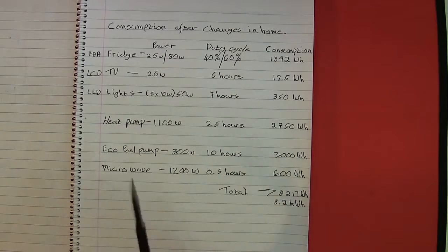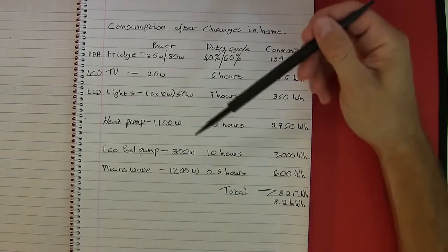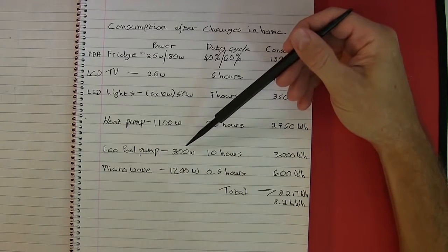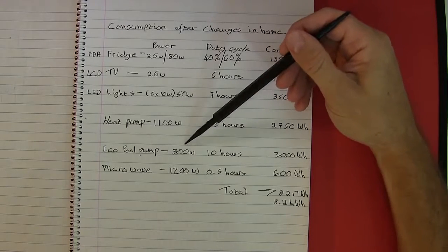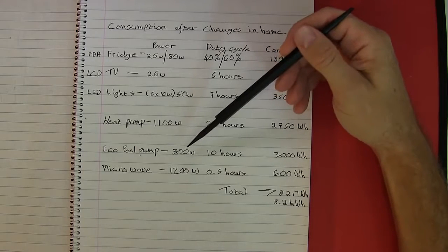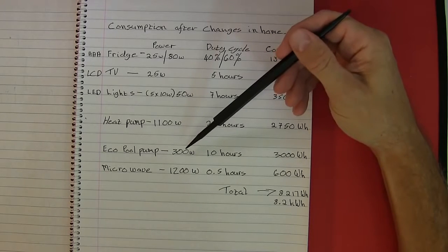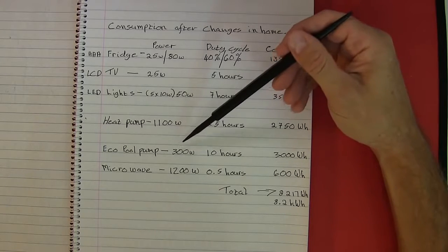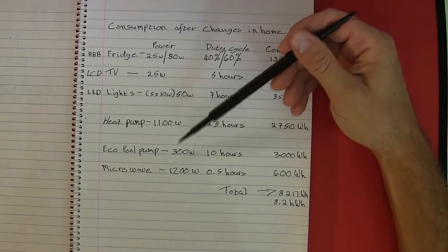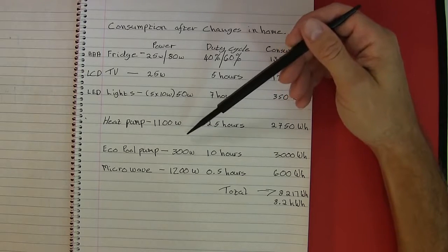And again, on the eco pool pump, as you saw mine, as opposed to running constantly at 750 to 800, 900 watts for 7 hours a day, I run mine at about 450 watts for part of the day when the sun's out and I know I've got solar power. It then drops down to 220 odd watts.